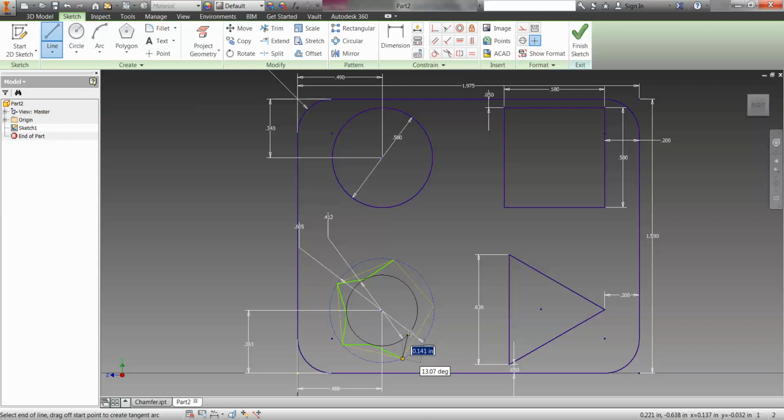So we have to be careful watching that we don't add any extra constraints in there, dotted lines that are unfortunate. Like here, we can see a straight line over, it's hitting a midpoint on another line. We're just going to kind of move it out so that we don't get those as we're working here. If we get some later on, we'll take those off. So we'll do the best we can to get things hooked up without too much extra on the lines. And so it's pretty good as far as the star shape goes now. I'm going to use the escape to get out of that command.